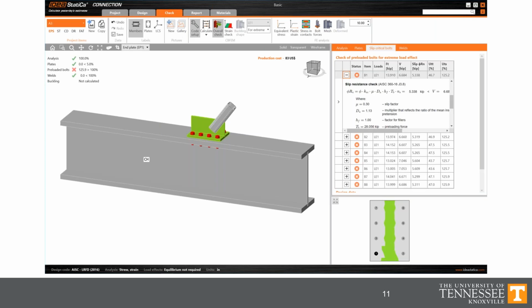And both of these are really determined in general iteratively. Sometimes you can calculate it directly in the traditional calculations, but the iterative approach was what we took in many cases. So for the AISC specification, or the traditional calculations, we can identify the maximum load, for example, by coding up the design equations in an Excel spreadsheet and then using goal-seek to identify the load that gets us right at the limit. In this case, the design example was pretty close. So instead of the 90 kips, 90.4 kips is the maximum applied load per the traditional calculations.